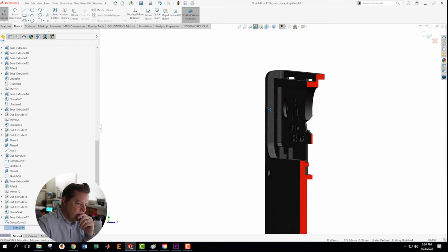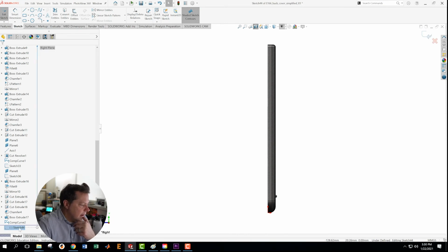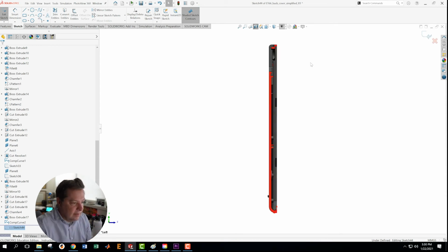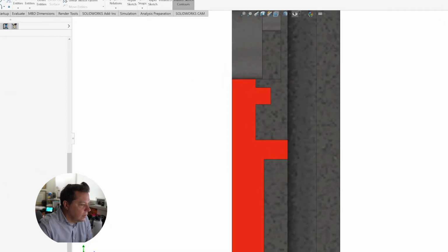Let's just check that one more time. Okay, yeah. When I make my cut right in here, when I say I want to watch this normal, it's probably going to flip it around to the backside again, which it did. And then I'm going to click that again to be able to get that into the right spot. I'm not sure why computationally it's taking so long to do that, but it's at least getting me where I want to go. Now I want to put a little rectangular cutout here.